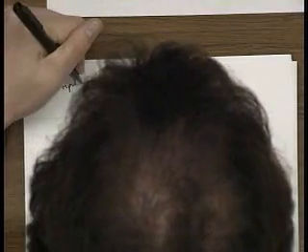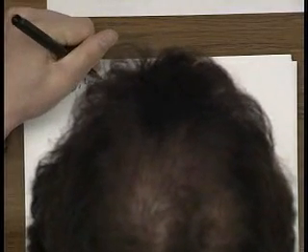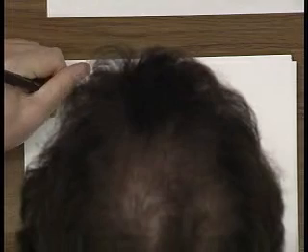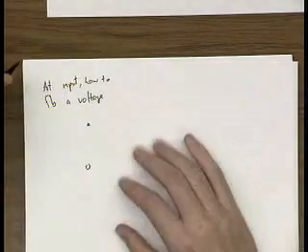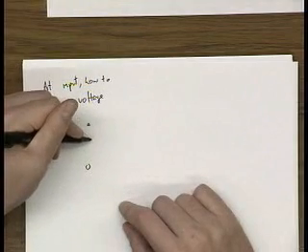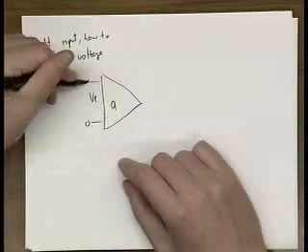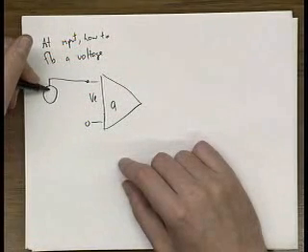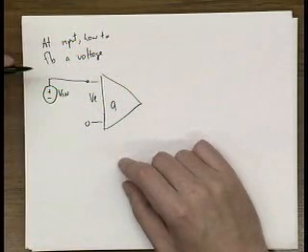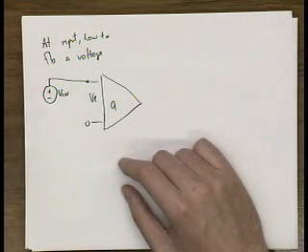Now let's look at the input. How do you feed back a voltage? So if you're applying here, this is going to be your V error that's going to go to your amplifier. You've got your V in here, but you also want to apply some V feedback.